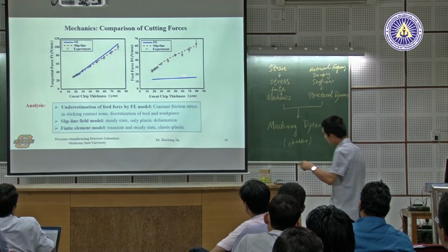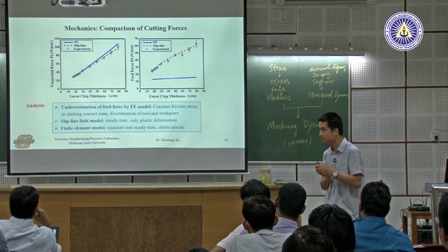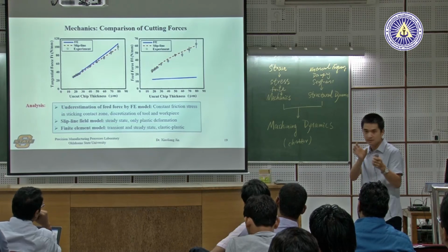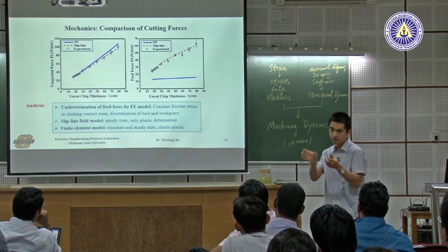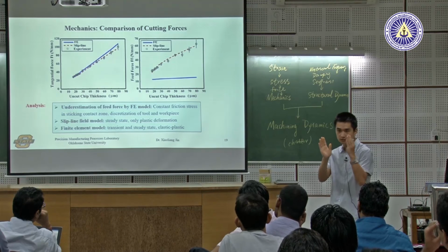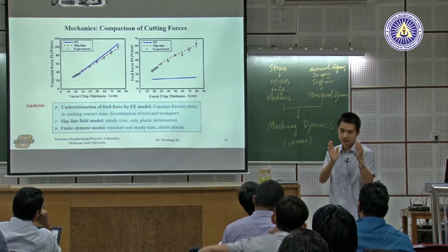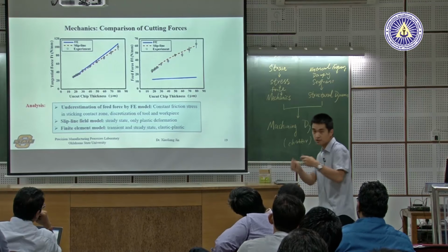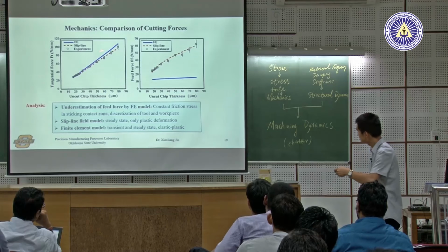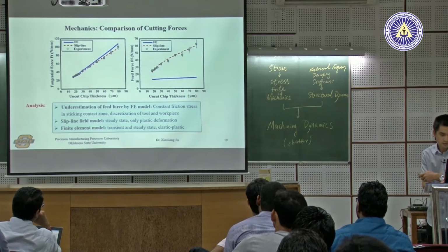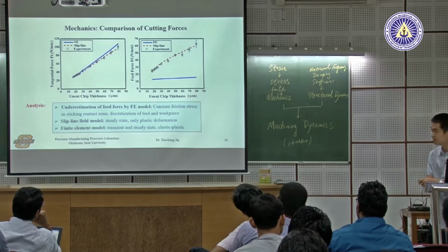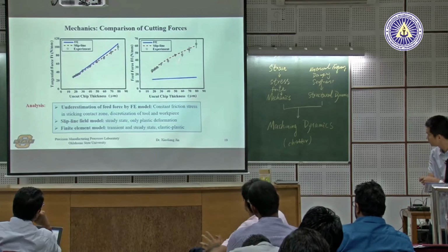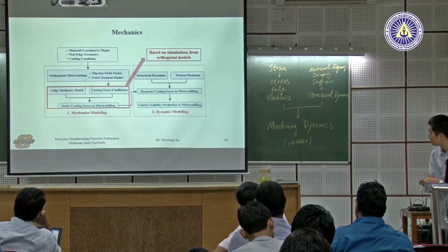So, I mean, we are still trying to analyze the problem, but we found out the feed force is mainly coming from the friction, right? And we found out even if we apply the same friction property identified from slip line, the chip thickness doesn't increase as we expect, okay? Then if the chip thickness doesn't increase that much, it causes a very small change of the feed force, okay? So that's still a major work we are trying to figure out, okay? But basically, it gives us some idea. I mean, there's a feed force discrepancy between the experiment and FE model, okay?